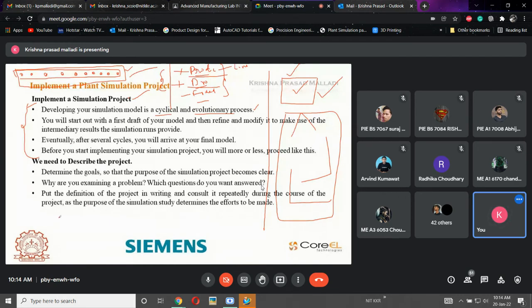I will explain simply. There are steps 1, 2, 3, 4, 5, 6, 7, 8. This is the process we have to follow. In this process, after 1, 2, 3, it will again come back to this one. In line layout, the product moves based upon the product. But here, it is based upon the process. If there is an oven or a heating process involved, the product needs to go to some other machine, and then come back to its position. So it works based upon the process.